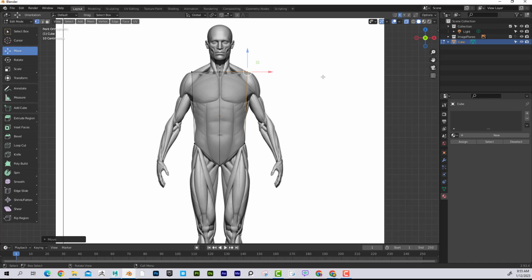Now, I'm going to start doing some more splits. I'm going to put a split this way right here because I can see that the image is kind of leaving us. So I'm going to hit Control R, and then I can kind of move this down like that, and then left mouse click again. And you'll see that instead of going straight through, it's slanted. That's because it's kind of averaging from its neighbors. And you can see that its neighbor, especially down here, is really slanted. So I'm going to grab that and move it down like this, maybe push it in like that, and maybe move this one up. And you can see how now it's aligning to the image a little bit better.